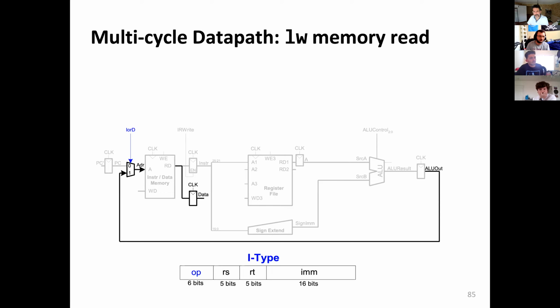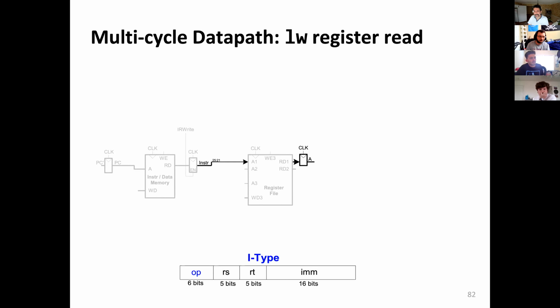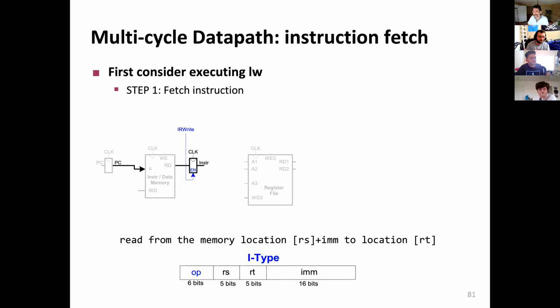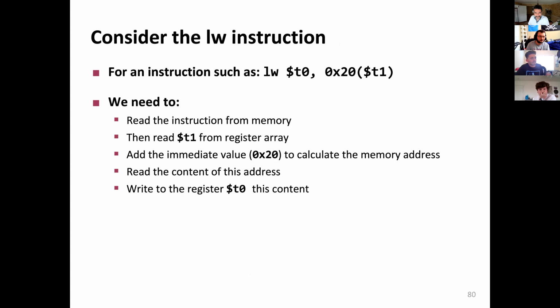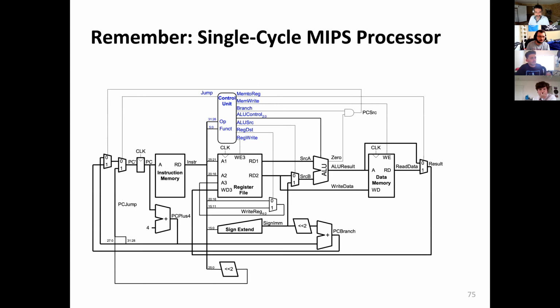Wait a minute, didn't we do the same thing in single cycle? We stored this directly in the register file. Why did things not go wrong here, but could go wrong there? And that's because we're working with multiple sets of data at once, because as one process is finishing, another process is beginning.